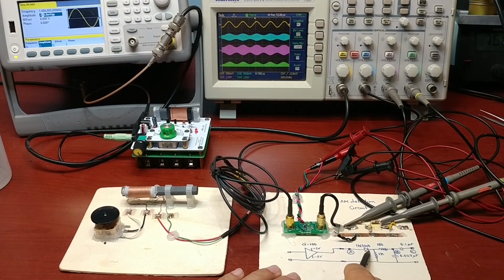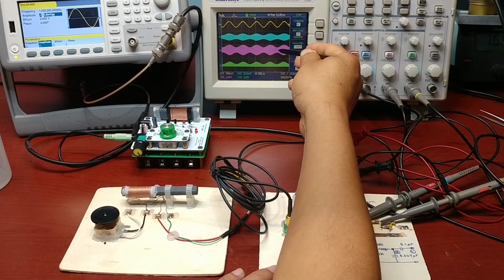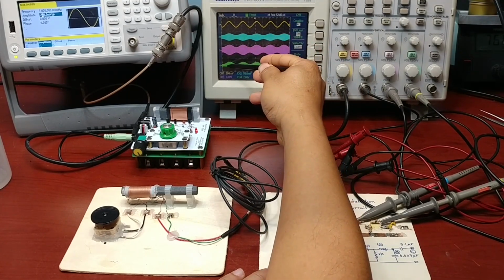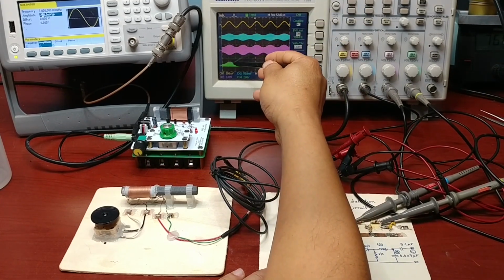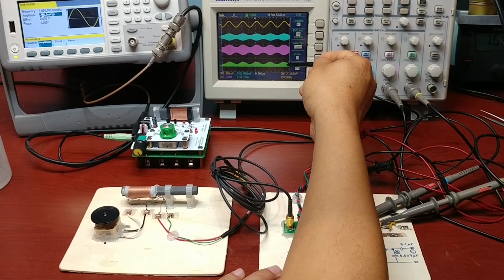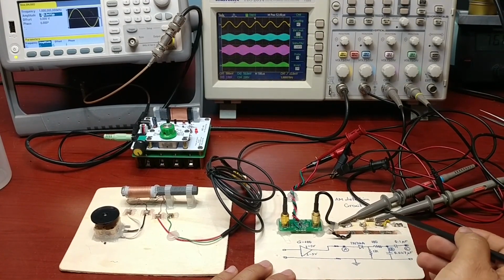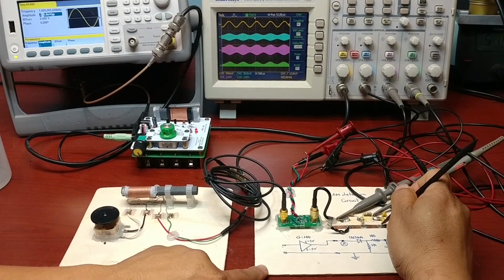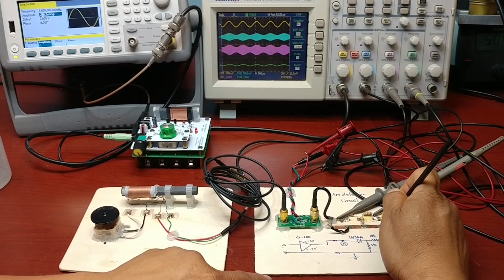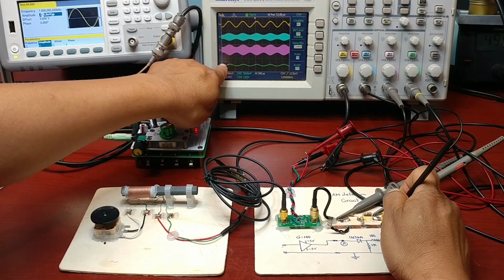When the signal goes through the diode circuit, we see the bottom half of the signal is cut out, leaving the top half of the signal. Inside of this condensed signal is the 800 kHz frequency, and the envelope is the 1 kHz. Currently, there is no low-pass filter in the circuit. We now connect the filter capacitor to the circuit. We will see the high-frequency 800 kHz is filtered out, giving a 1 kHz sine wave at the output. When the capacitor is connected, the output signal becomes a sine wave signal.